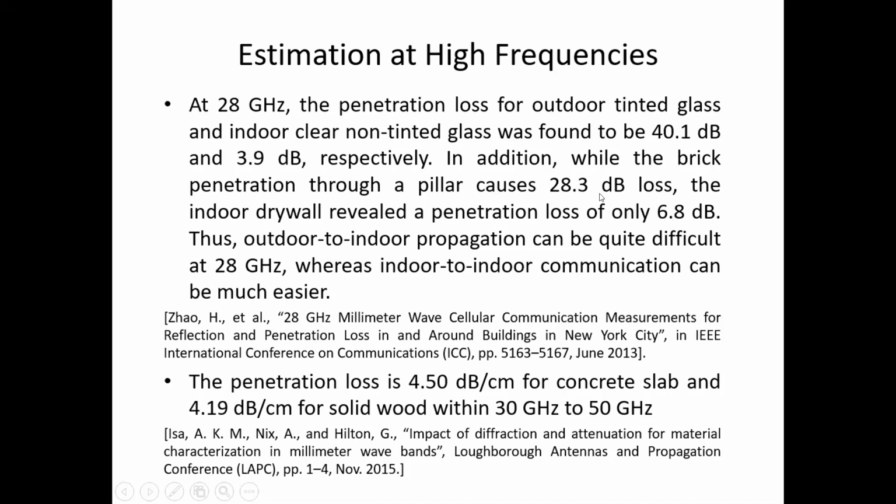This 28.3 dB loss we have through a pillar, which must be made of concrete, and in the case of indoor drywall, which is made of brick, you have a loss of 6.8 dB. So again, you see there is a large difference. All these differences are a lot more for high frequencies.